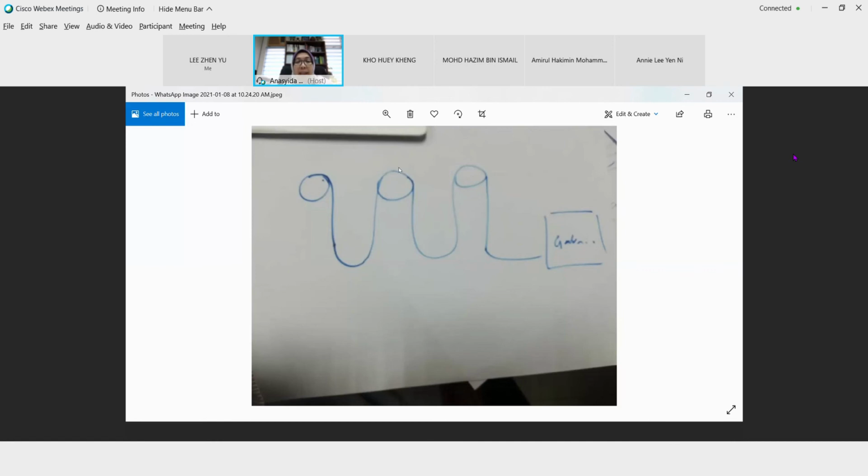So when this process is complete and goes to cleaning and so on, and during the dipping process, it will have a dent. So the coating is difficult to adhere to the dent area. So what happened here? There will be gas entrapped in this process. After galvanizing, the gas will burst out and form a pinhole.